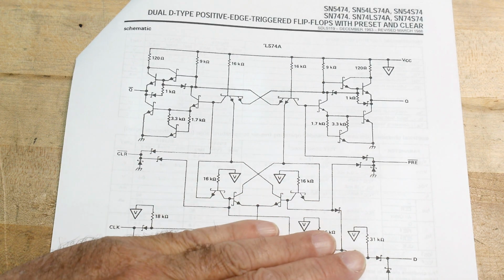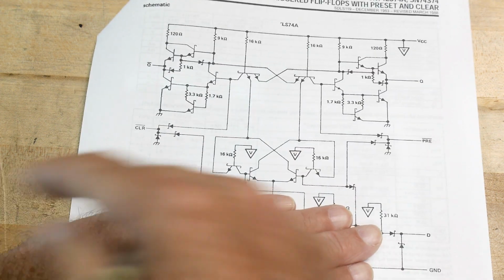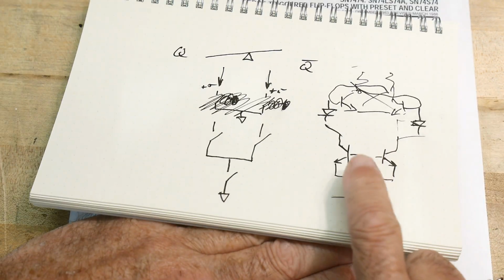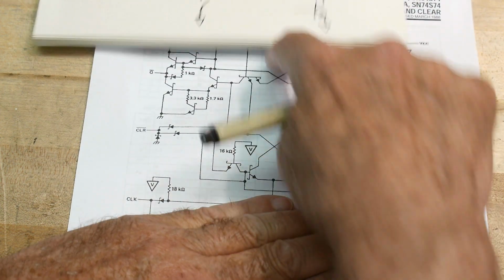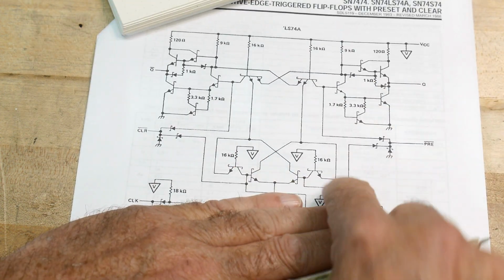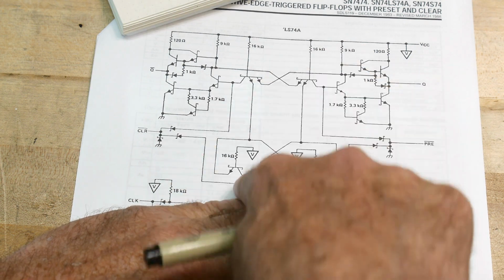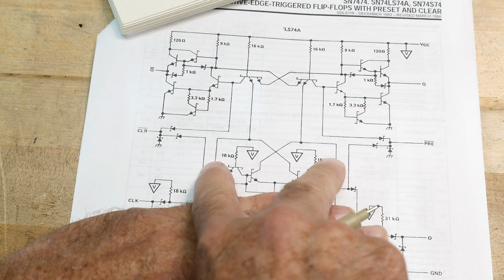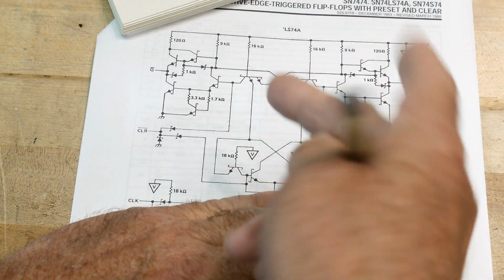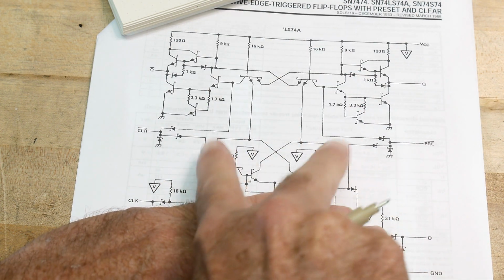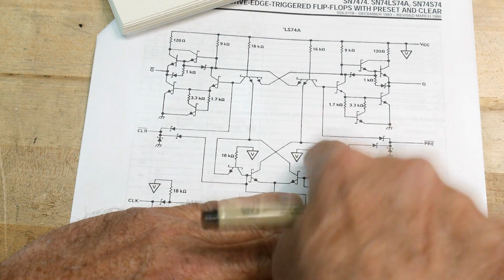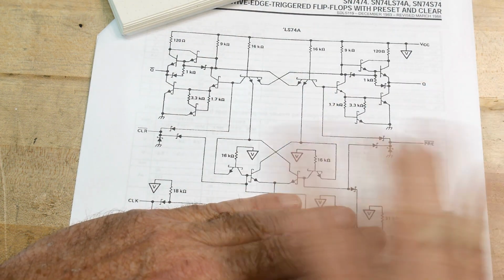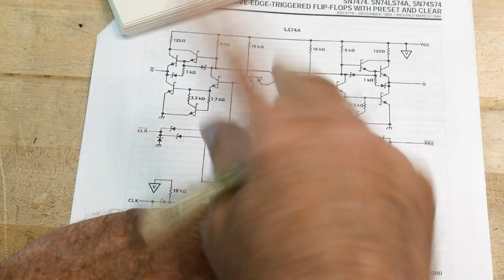And then we've got these transistors, which are these bottom two that I drew here, right? This transistor can pull down over here, and this transistor can pull down over here. And look, they're in a flip-flop state also. They can't be the same. They're always opposite to one another. You can either have 1, 0, or you can have 0, 1. But you can't have 0, 0, you can't have 1, 1, okay? So it's either one or the other.